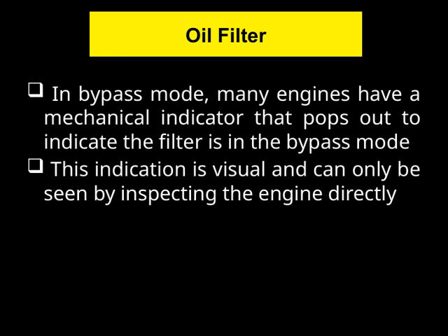Specifically, with the oil filter, this bypass indicator serves as a critical alert. It's designed to warn us that the filter might be bypassing, which could mean there's a blockage or some other issue needing attention. Recognizing this indicator helps us maintain proper engine health and ensures that we're aware of potential problems early on. Overall, this visual cue underscores the importance of routine inspections and being attentive to these mechanical indicators, especially when we're managing engine performance and longevity.